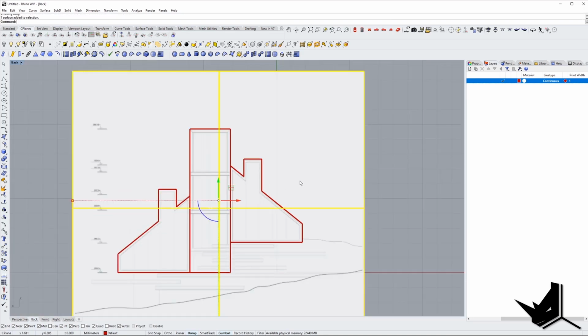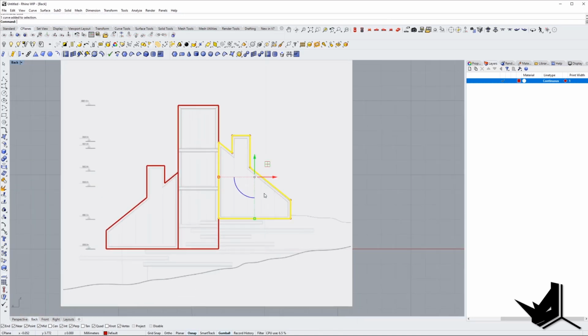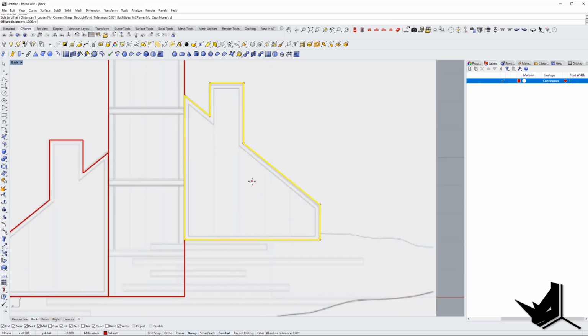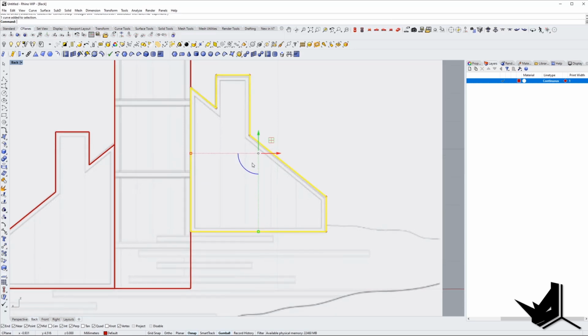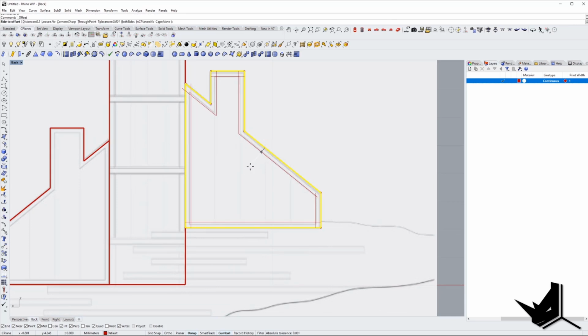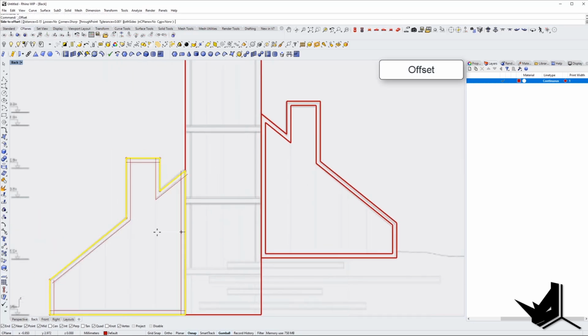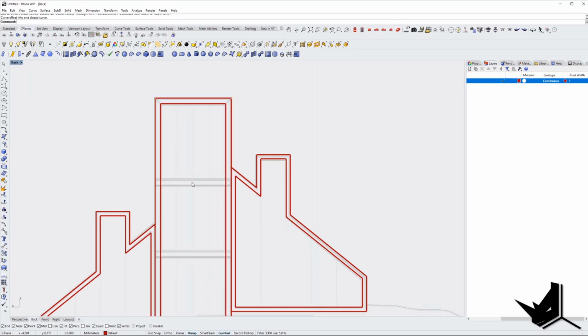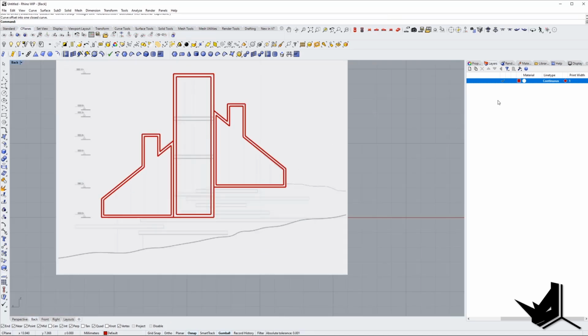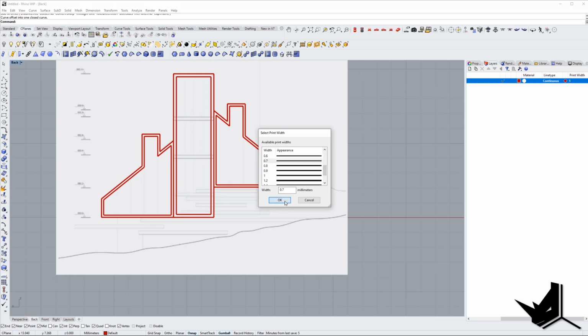Now let's do the offset. Let's lock this guy. And I'm gonna do offset here. I should put maybe 20, too much. Let's do again offset of 2, too much. Offset of, let's say 0.2. Yeah, that's close. So I'm gonna say distance of 0.15 on the inside, and that's it. I'm gonna do the same here, and I'm gonna do the same here. Here it's a little bit more, so I'm gonna do offset 0.20 inside. There you go. And let's lower down a bit now this thickness.